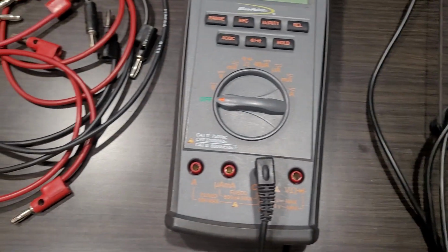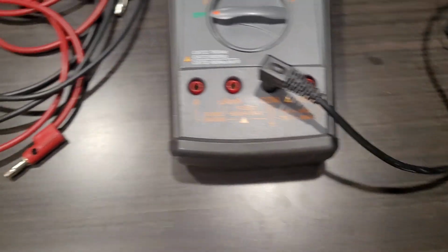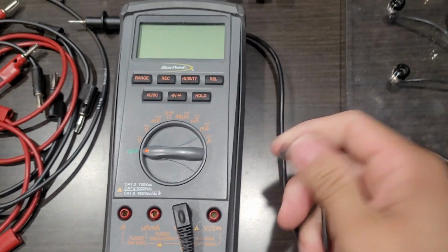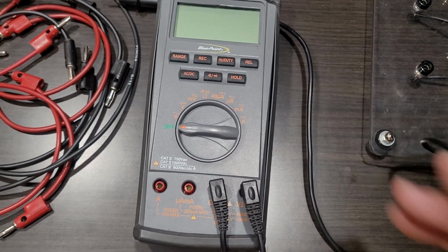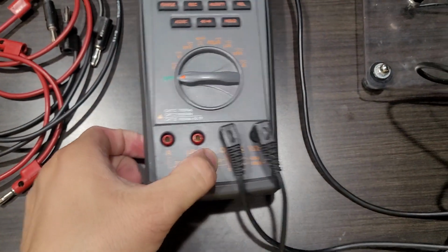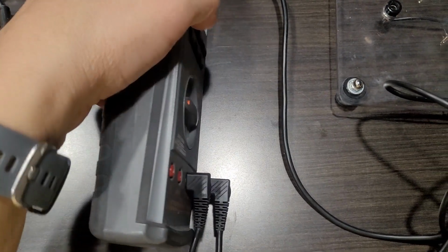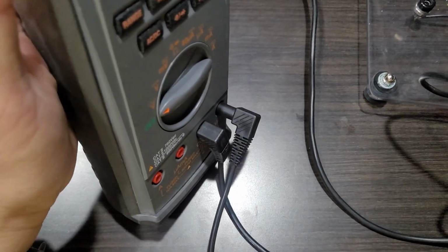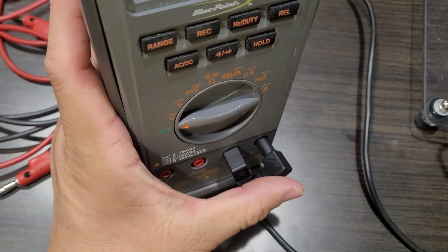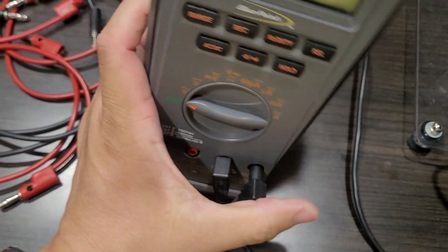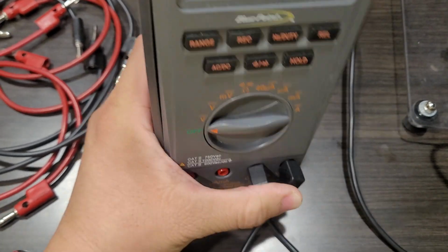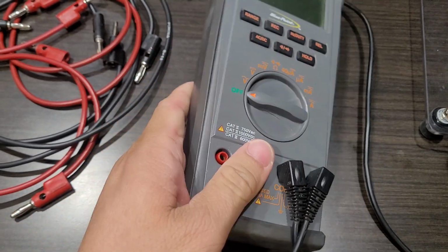One of the problems I see students doing all the time. Now, when you're looking at me do this video here, it is from the top, so it's hard to see, but I'm going to flip this digital multimeter over so you can see what I'm talking about here. Lots of times students will set this up and you can see the difference in height here, okay? You want to make sure this test lead is fully pushed in, okay? Make sure you push it all the way in to get a good connection and a good reading. So there he goes. Make sure it goes all the way in.